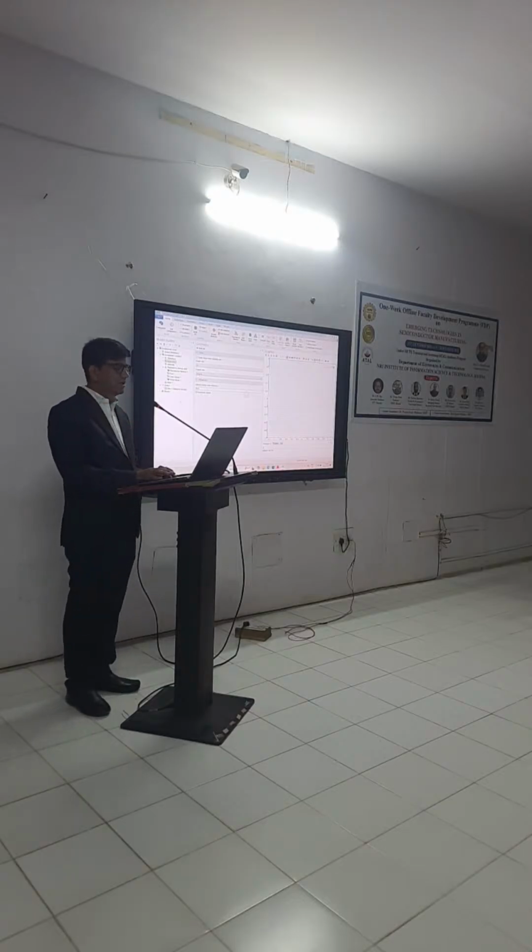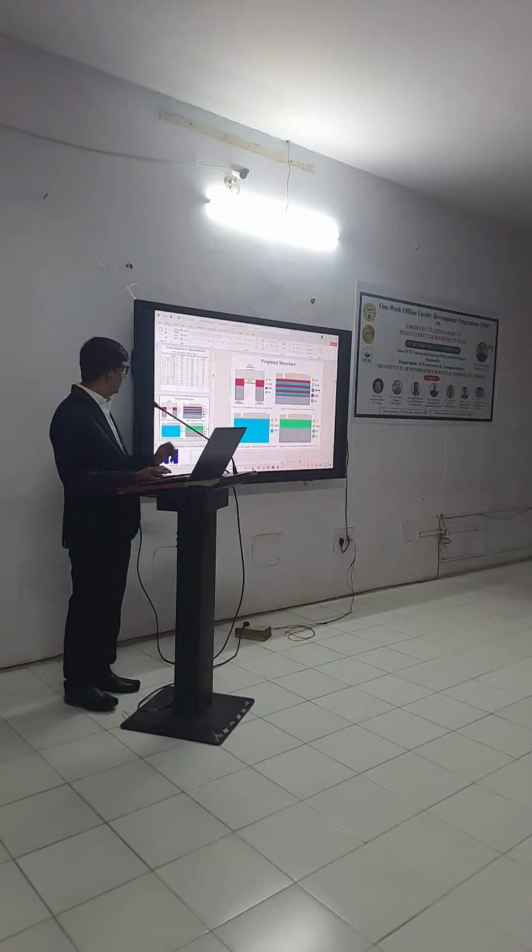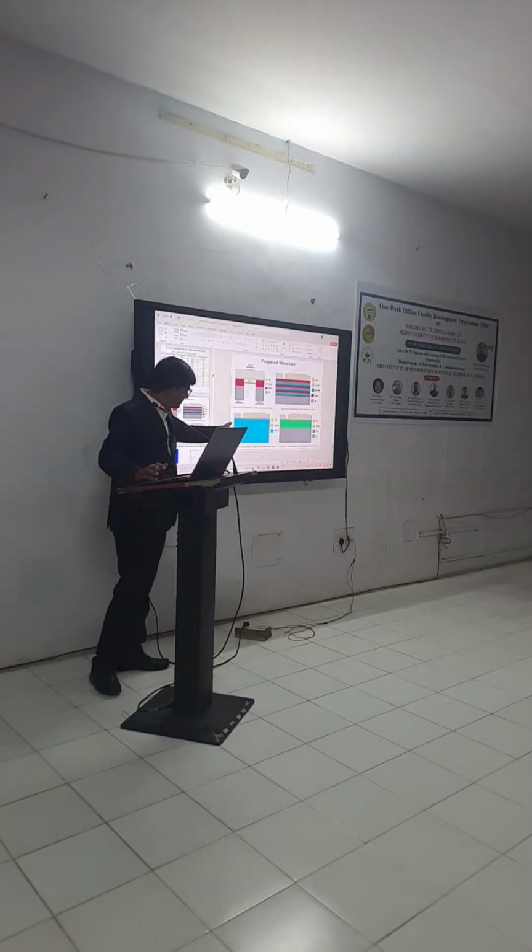So in this geometry part, first we have to select length in meter. Generally these are MEMS devices, and what is the device size? Always in micron. So here, instead of meter, we will select micrometer. Then what is the structure of my device? I have this PET substrate, over which I have an aluminum layer.